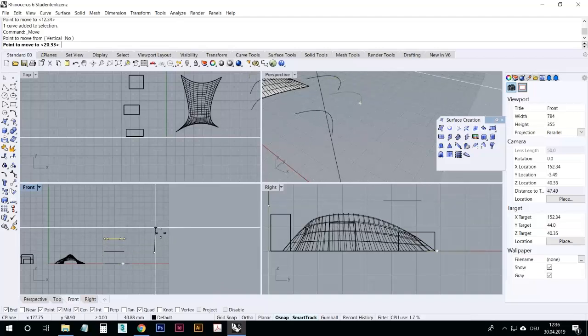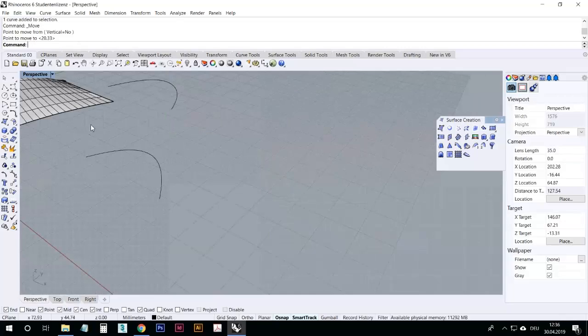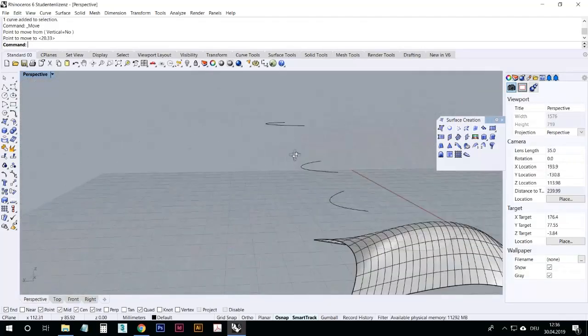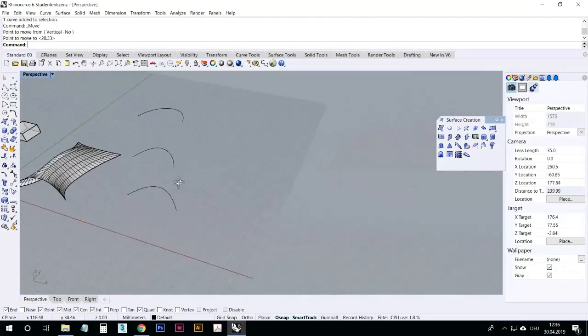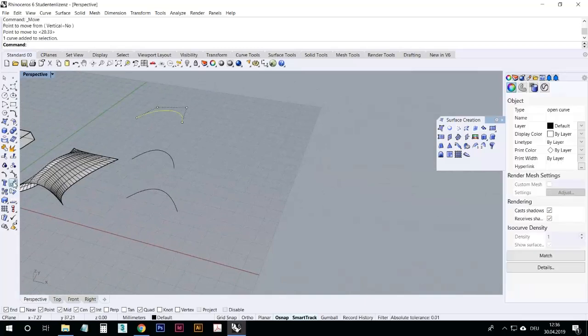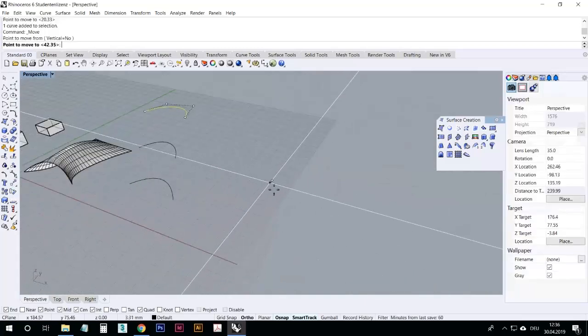And you see that it mimics the movement, of course. So I pull it up somewhere like that, and then we can start choosing, building our loft. Now I double clicked again to the perspective view, and you see that they are lying like this in Z space. You can always move them if you want to rearrange it somehow. You can hold shift and go back and forth like this, like I'm doing now.